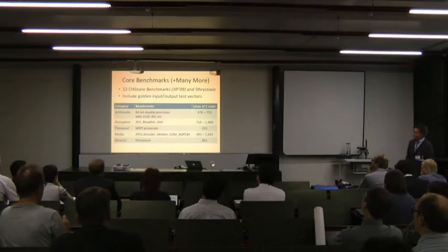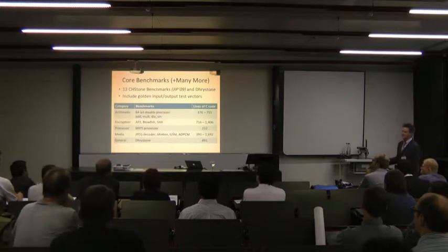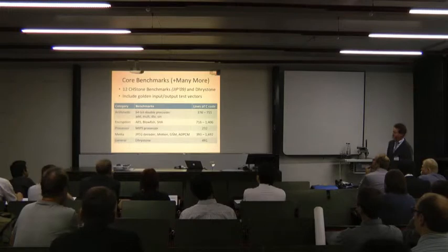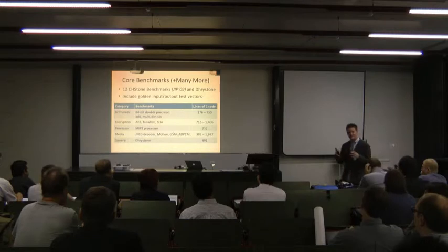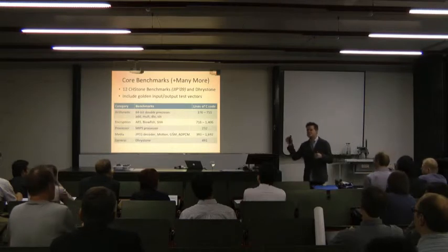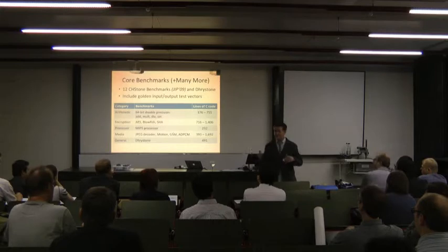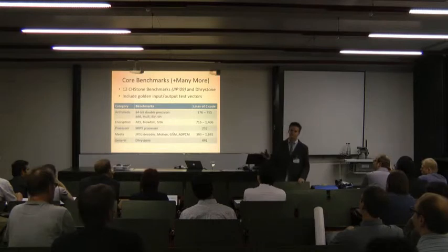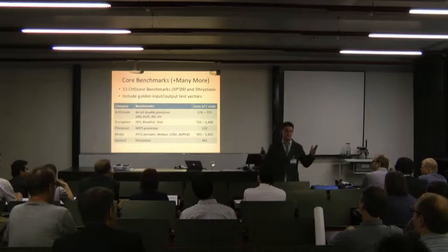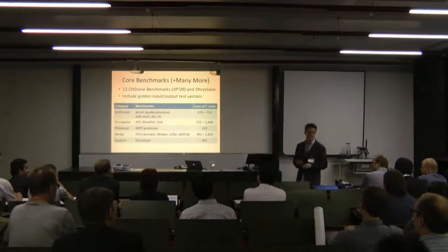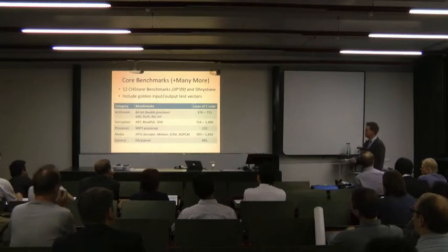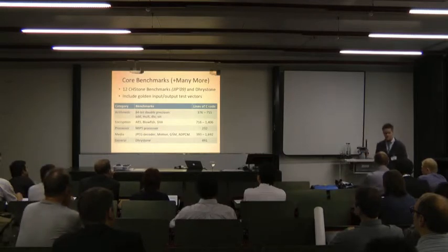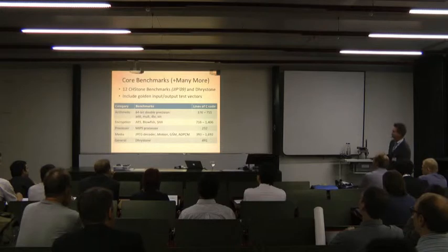Now, when you download LegUp, you get many benchmarks, including the 12 CHStone benchmarks, which came from a university in Japan. A beauty of these benchmarks is that the input test vectors and output correctness checking is actually part of the benchmarks themselves. Okay, so the benchmarks have within them injecting vectors and making sure the output is correct. That's of course beautiful when you start a project like this, because when you're writing your own high-level synthesis tool, of course nothing works. Of course, you're getting the wrong logic functionality. At least with these circuits, you can tell, are you getting the correct answer? And they come from different domains: arithmetic, encryption, processor, and so on, media.